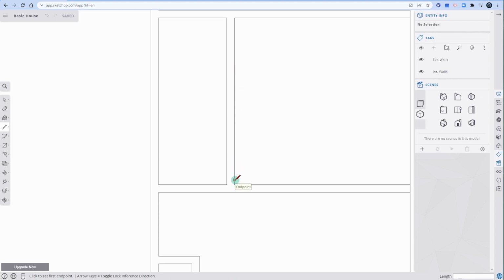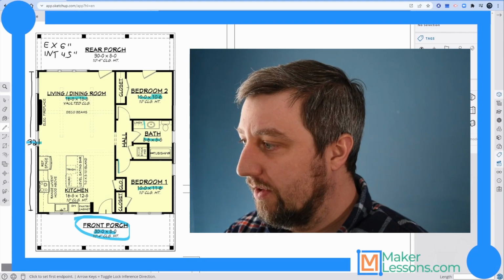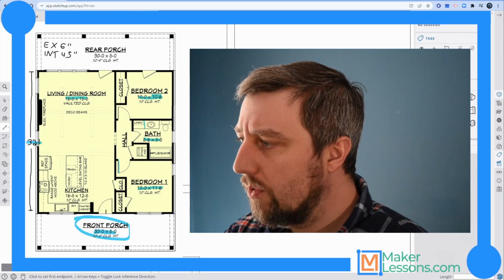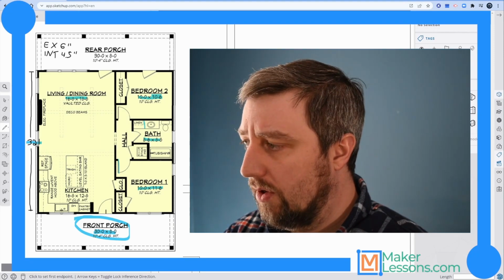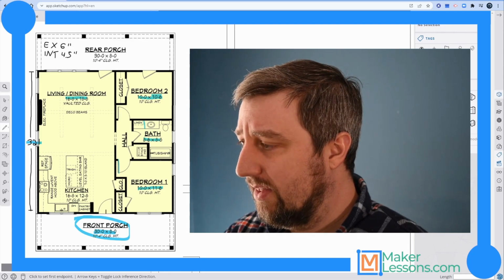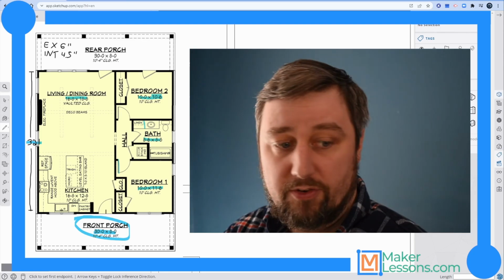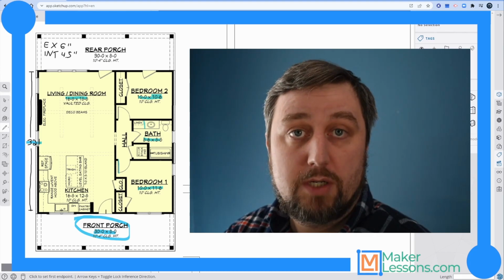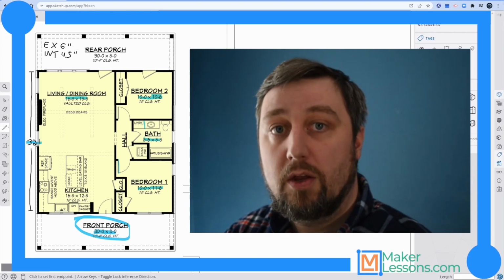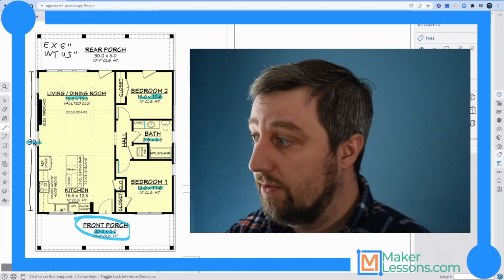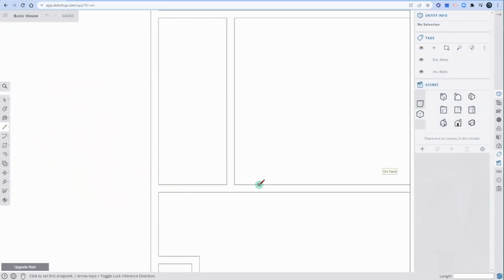So the other side, if you look real quick, it just gives us door jamb, door jamb, then we have a wall, right? And this wall looks like it's even thinner than a regular wall, but we're not going to change that. We'll keep it the same. So door jamb 4 inches, door 32 inches, door jamb 4 inches, so it's 40 inches up before we get to this wall there. I'm going to go from this corner here. I'm going to go up 40, enter, mouse over till I get to it. There it is. Chop it.